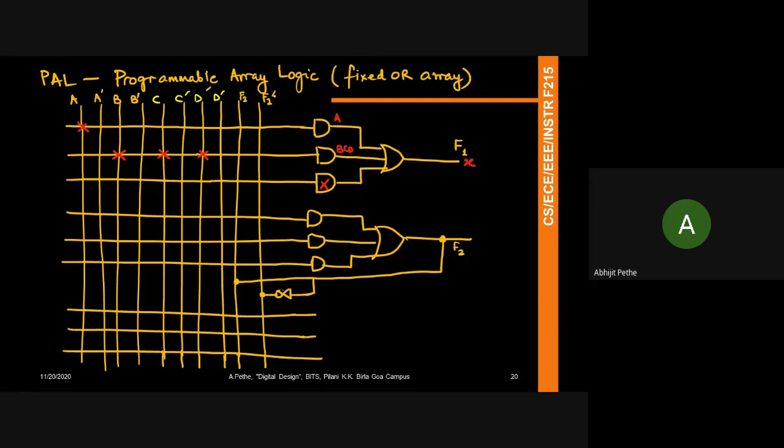So it gives you the flexibility. Normally if you look at PAL chips, some chips give you this flexibility and it's normally given to one input. In this case, it gives this flexibility in F2. Normally it's given in the first, let's take this here. And so I have another array which looks like that. Let's assume that I have this array, which consists of 3 outputs and 4 inputs, and one of the outputs can be treated as an input to the next stage. Now, why is this important?